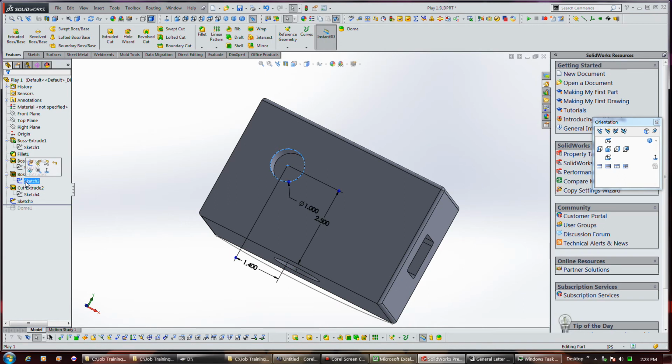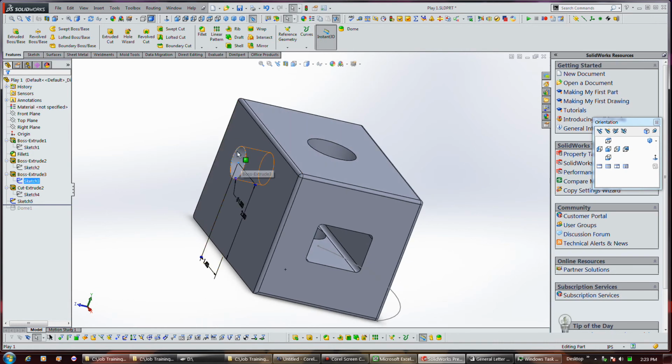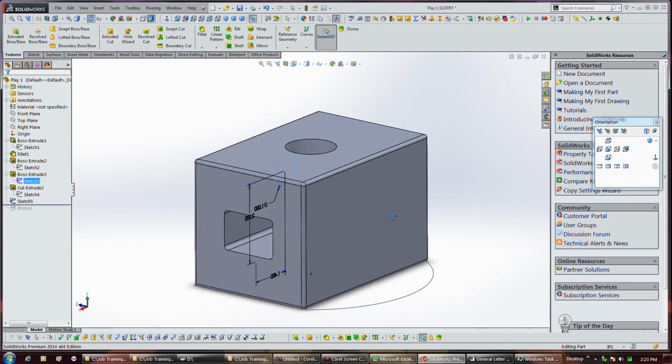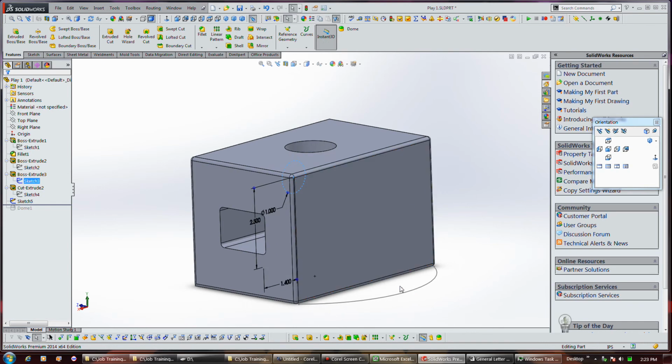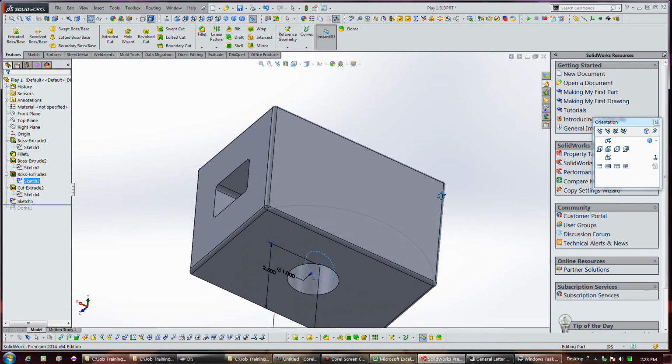Yeah, I referenced it to the origin point of that sketch on that face. Because that one I just pre-drew. I just drew it on the side, without a plane. I just chose circle and just drew it. So that's where that came from. That's why it doesn't really have, quote unquote, a plane. But this one, again, I don't think we can move because there's no reference plane to it. So I'm going to have to go create an offset plane.